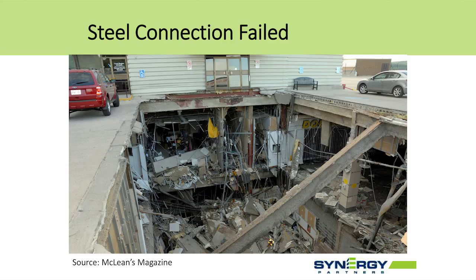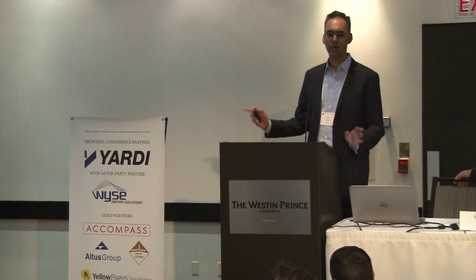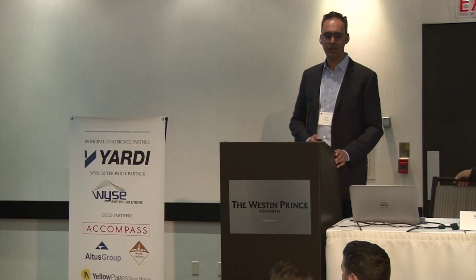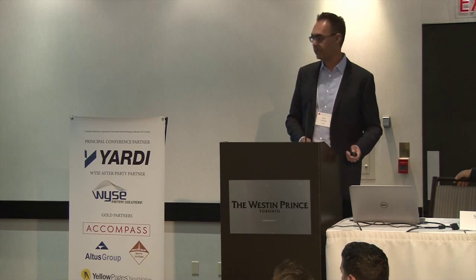And unfortunately, this beam that you see lying across the big opening here was the main culprit. And the connection where that beam interfaced with a column was the main source of the failure. And it was just corrosion. It was as simple as a parking roof deck, cars bringing in road salt, leakage over the course of multiple years. There's debate and arguments over whether the design was inherently flawed, but regardless of that, there was ongoing concealed corrosion for decades, and it resulted in a massive failure. And so it's something that could have easily been prevented.